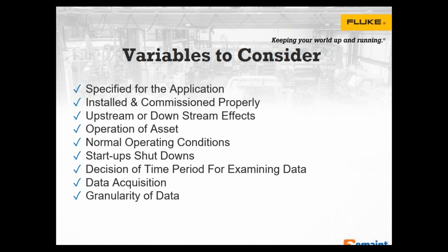If you talk to the programmers, they only have so much room. It may be a Modbus type or 4 to 20 type signal, but they can only handle so much data, and there's only so much room on these servers. So it's not uncommon to have non-granular data coming in some cases.